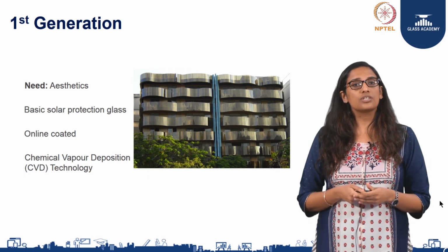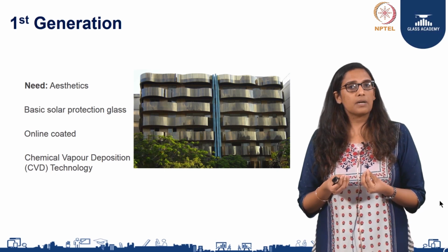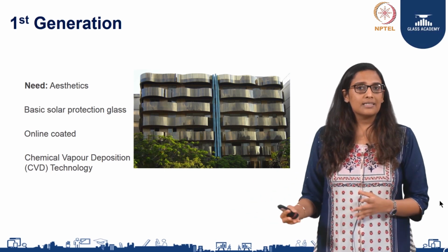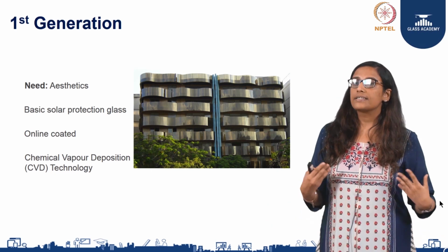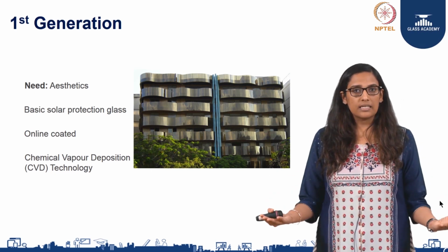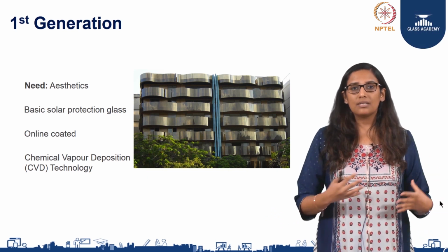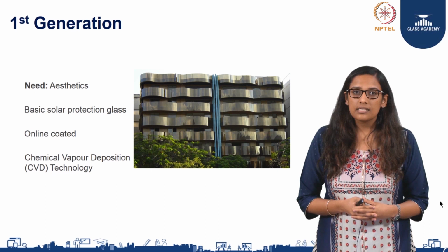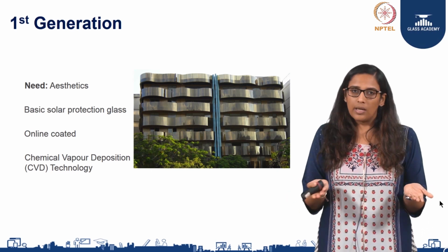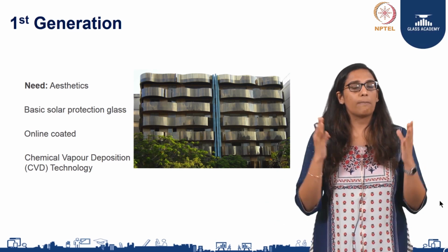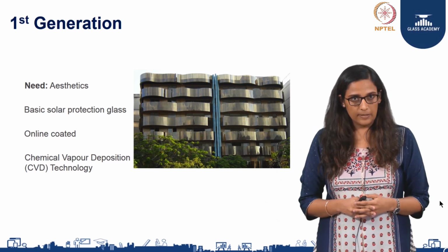This particular solution was ideal for the mass market, but really didn't yield to a lot of the other advantages that people were looking for. It didn't yield well to the processing requirements, if glasses had to be value added, if it had to be tempered and laminated, and if the glasses had to be more subtle colored. Well, it wasn't possible because there were very, very limited options that were possible with the CVD technology.